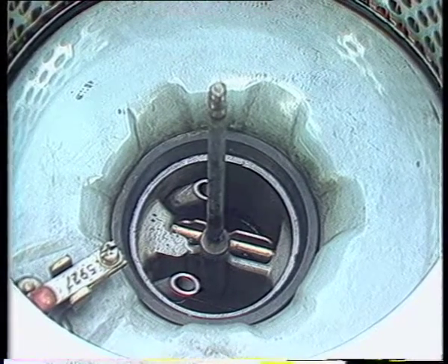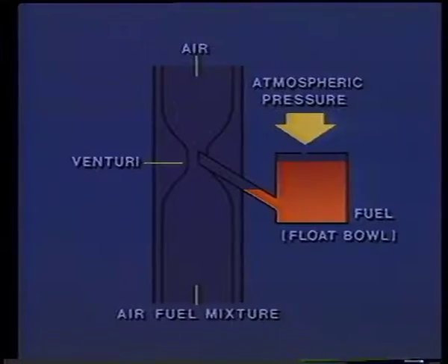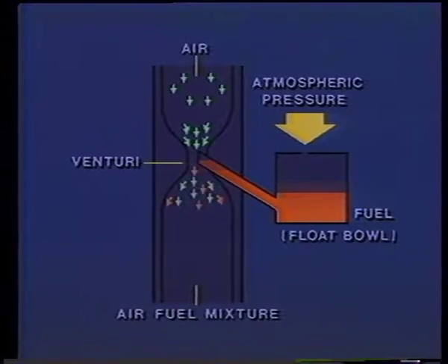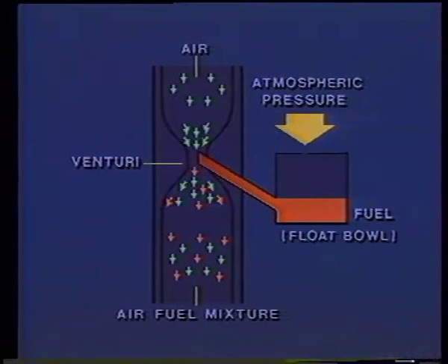It means the valve chokes off the airflow. Then, when the engine is cranked, a fairly high vacuum develops in the air horn. This vacuum causes the main nozzle to discharge a heavy stream of fuel. The quantity delivered is sufficient to produce the correct air-fuel mixture needed for starting the engine.